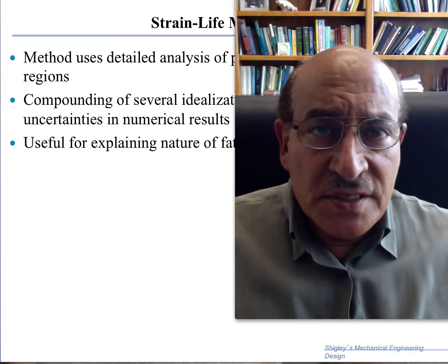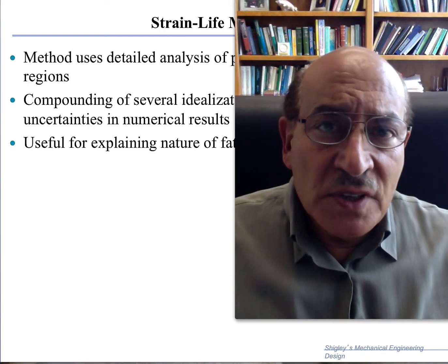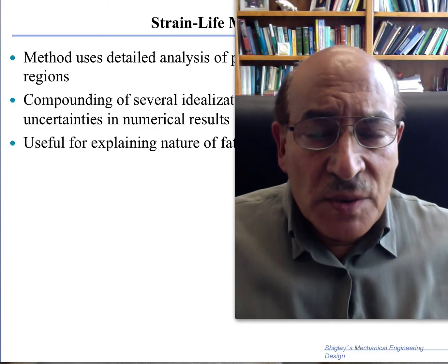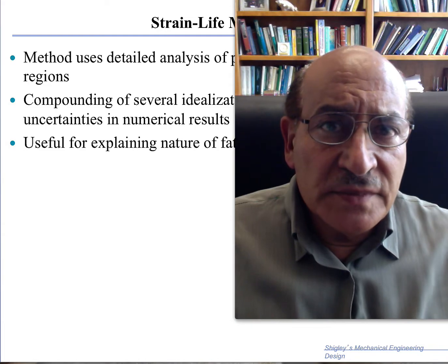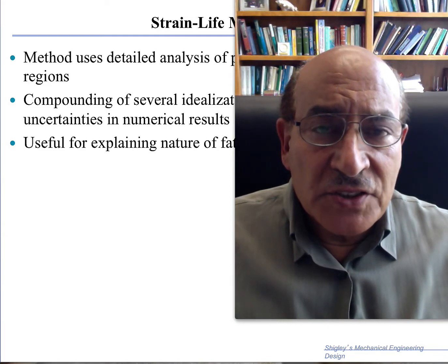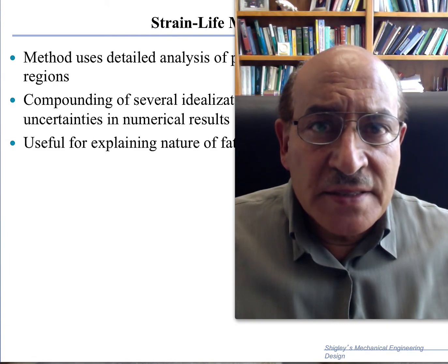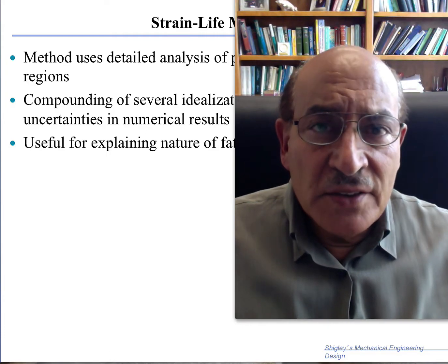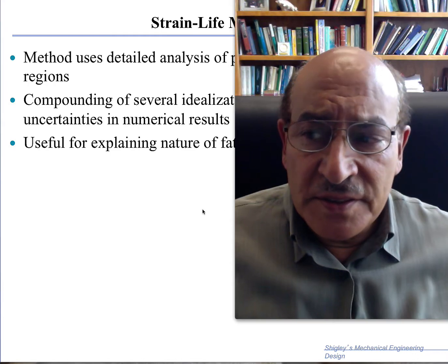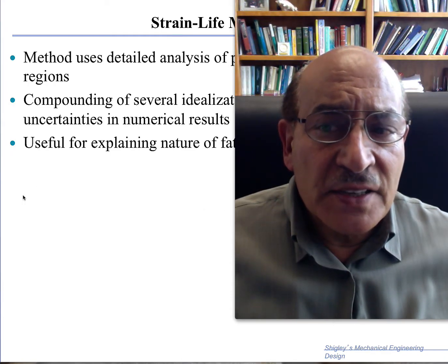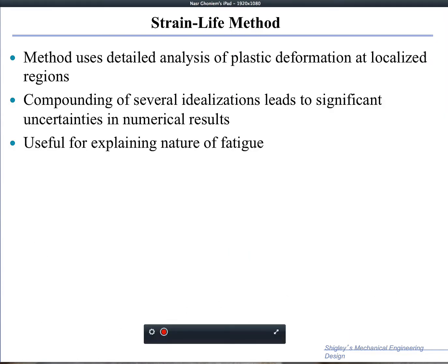So in these situations, we have to pay attention to ductility. And more recently, there are efforts to include linear elastic fracture mechanics as an additional tool for analysis of fatigue life. So let's first consider the strain life method and then move on to the linear elastic fracture mechanics area.